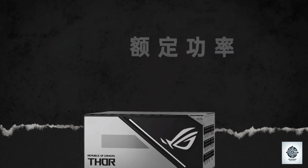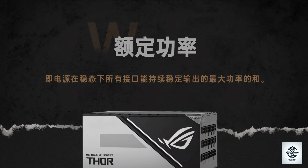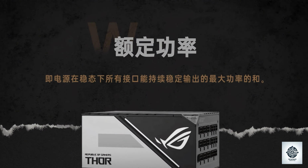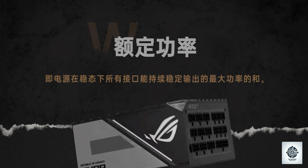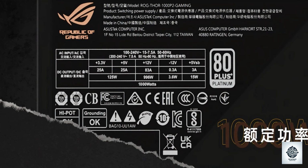The power rating of a power supply is measured as rated power, which is the maximum power that the supply can continuously provide under stable conditions. For example, a 1 kilowatt power supply can deliver a total of 996 watts through its official outputs. Two main outputs of this power supply can deliver up to 83 amps, equivalent to 996 watts. The 5-volt and 3.3-volt outputs can provide separate currents up to 25 amps, and the total simultaneous output power of these outputs does not exceed 125 watts. The -12-volt output is now hardly needed for computers, and its power is quite low, so it can be ignored.